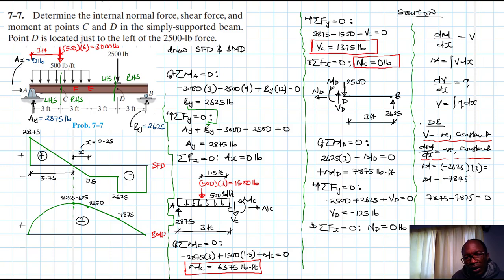And then for the internal forces, it is the section D. We have MD equal to 78.75, and that one we found it was the exact value there, right? 78.75. And then we had the negative shear at D. We had 125. Let's check. 125, great. And of course the normal force, as usual, we expected it to be equal to 0. Right. So this is about it, really.